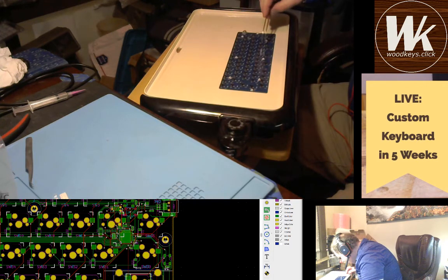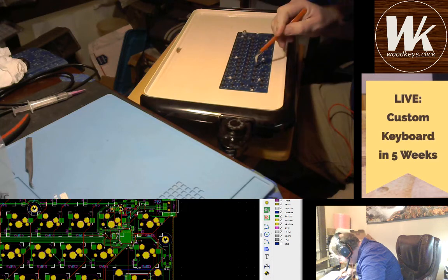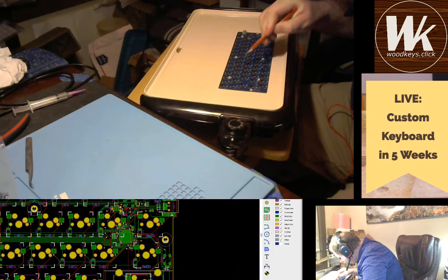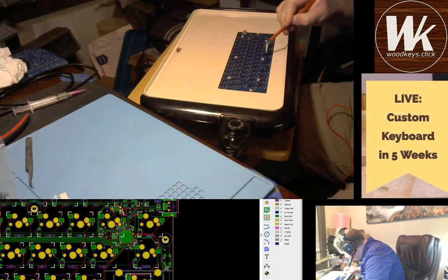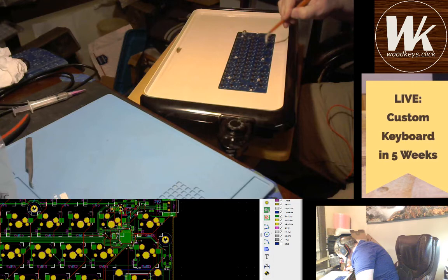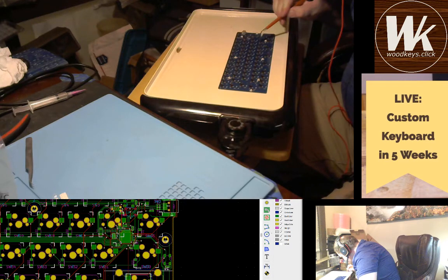It looks like they're all, these sockets look like they've either pulled up a little or just didn't get pushed down right. Those in there. Looks like the controller's reflowed over here. All these components look good. Speaker kind of came off.